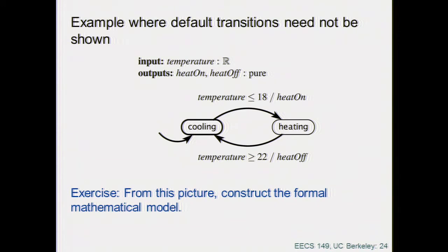Say it again. If the output, by that argument, you want to show that outputs remain switched on when you're in a particular state, right? So in the garage counter example, if we are implementing the old semantics. Yes. So if you want to have a complete finite state machine, yes, I should. So if nothing happens, not up, not down, I stay there, right? And so that would be an explicit default transition, okay? But in that particular case, if I assume that the display of the counter is a persistent signal, then I don't need to show it, because my output is not changing.